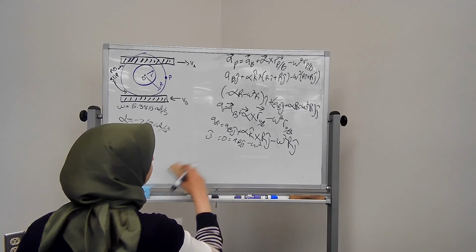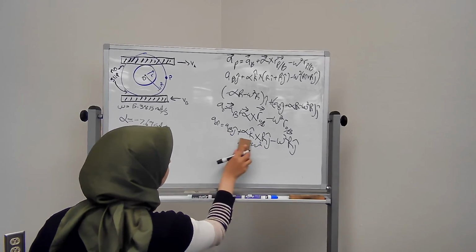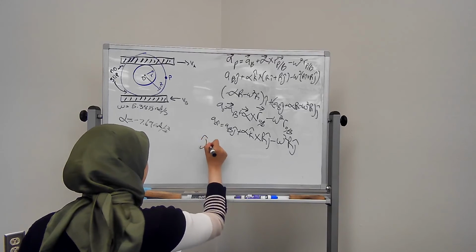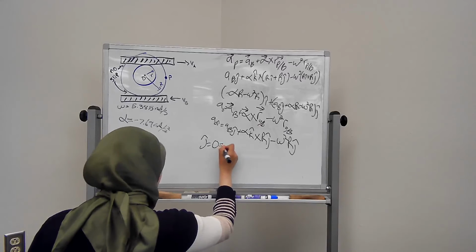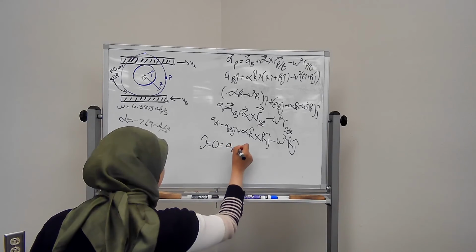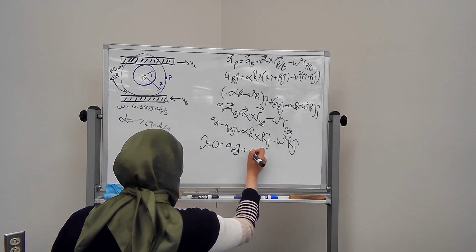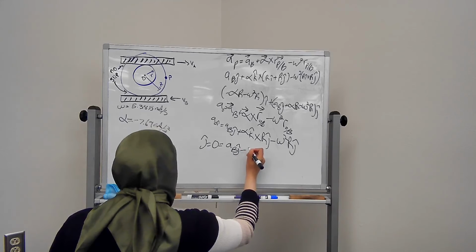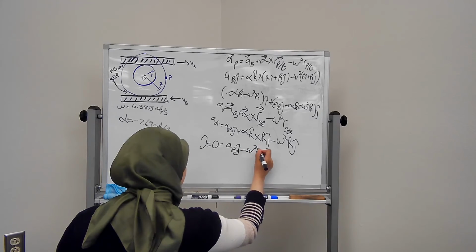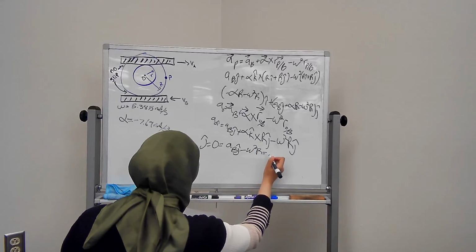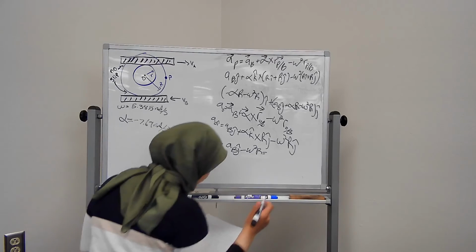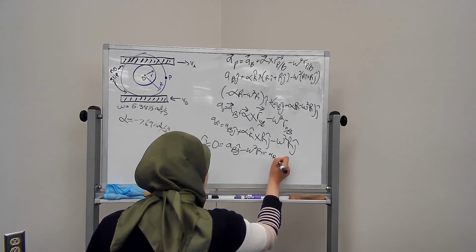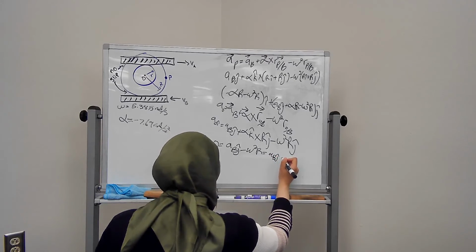So one thing we can do is solve for that using the acceleration equation that we've used so far throughout this problem and in this chapter. To set up that equation, we get the acceleration at point O is equal to the acceleration at point B plus alpha cross r of O slash B minus omega squared times r of O slash B. As you work through that, you can do the cross product and simplify all the terms, and you can get that the acceleration at B in the y direction is equal to omega squared times r.